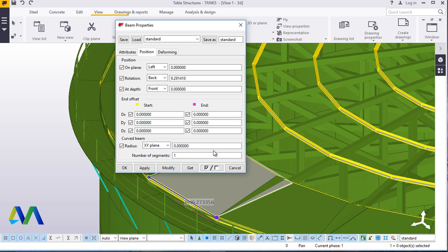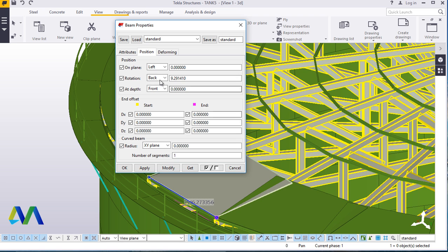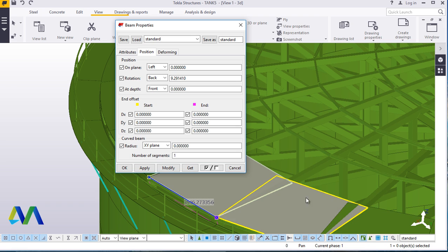Just do it one by one, just to avoid the confusion. You know, every plate has its own set back rotation angle. So if you select everything in one go and do a uniform increase of segments, there will be a variation, and the bending profiles of the plates will conflict.